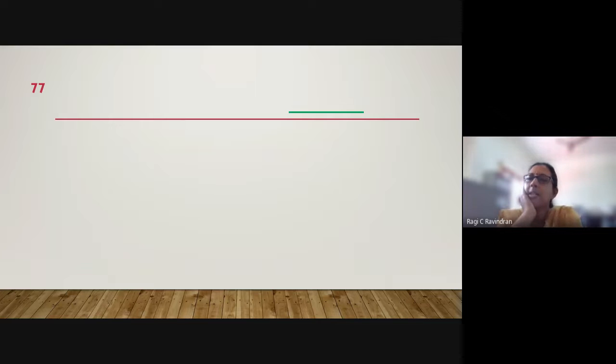Now, let's consider a level surface. The train was initially moving over this level surface, and suddenly you come across a curve, so you need to provide a super elevation. The darker shade of line indicates the inclined line which connects the top portion of your outer rail and the top portion of your inner rail. And this is the deviation.